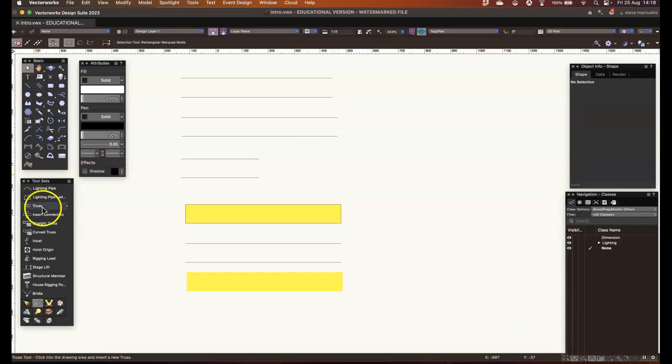The control line comes into play with the walls tool as well. The walls tool there has exactly the same control line thing because it's critically important which side of the wall you're drawing. The double lines we tend not to use for walls, although you can turn double lines into walls, but at the moment I'm just showing you lots of tools to play around with. Have a go at the line tool.